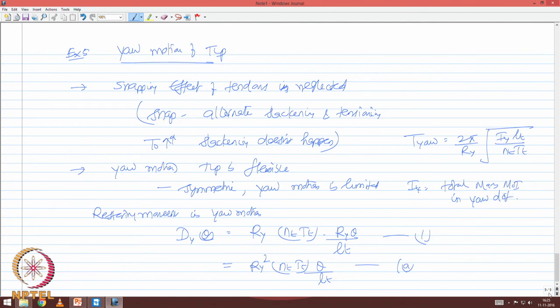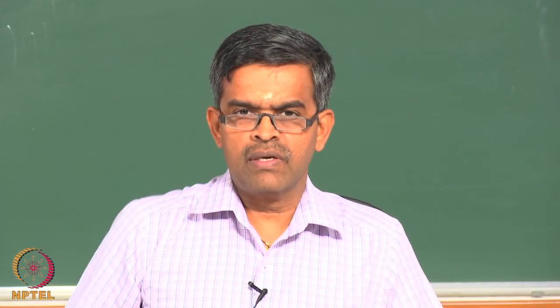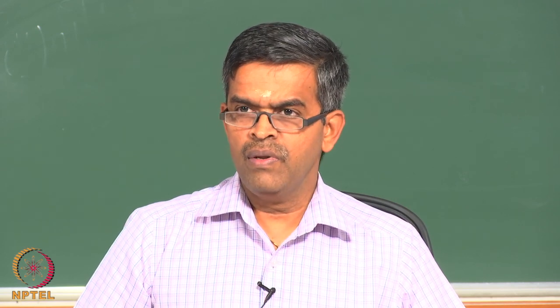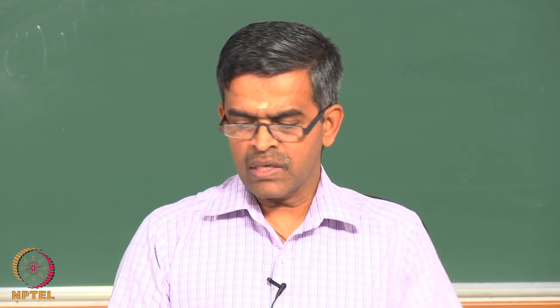So, friends, in this lecture we are trying to understand through simple examples and equations how we can estimate the restoring force, the initial stiffness, and periods of vibration for different varieties of offshore platforms under simple normal free vibration conditions. Now, the question comes, what is the necessity for new generation platforms? There are some lacunas which the existing platforms had.